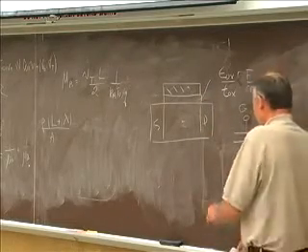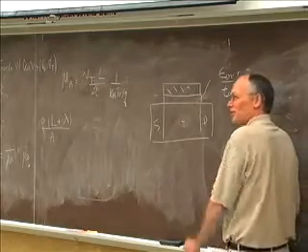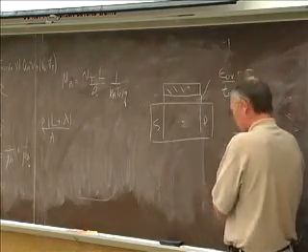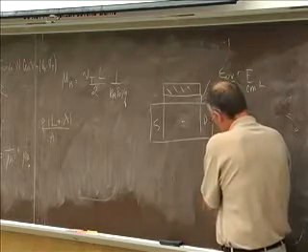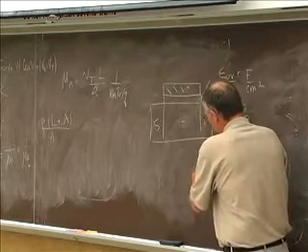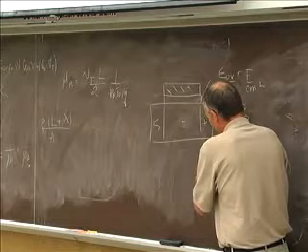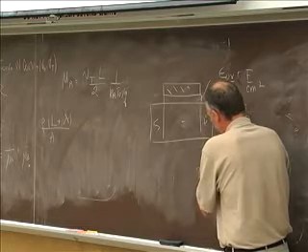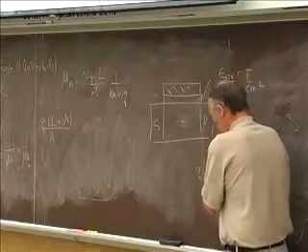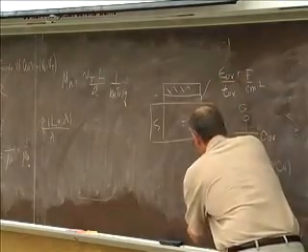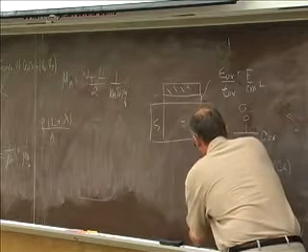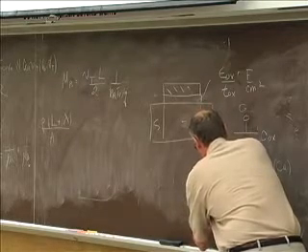And this probably won't come up in your lectures later on, but you can show that this semiconductor capacitance under simple conditions is Q squared times the density of states at the Fermi level. The 2D density of states is effective mass over pi times h bar squared.